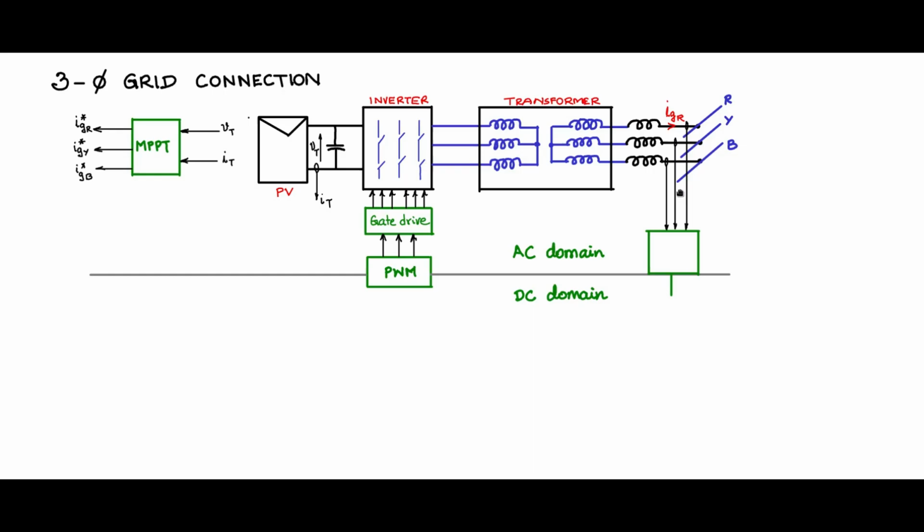Let us say the currents that you are sensing are sinusoidal signals, and after you pass it through this transformation, what we call frame transformation, the variable here, even the current variable here, will appear DC. So to the controller, as the variables are appearing DC, I can now make a set point controller. Now that would give a much better response, and the controller will also be simpler and have a better bandwidth and better performance.